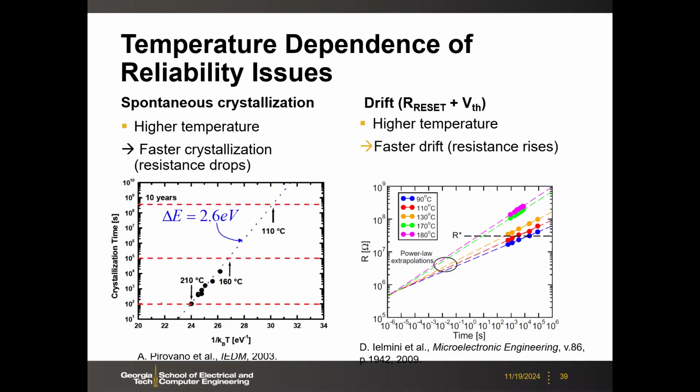That means the device tends to move from the high resistance states to the low resistance states. If you have some temperature, that will accelerate this recrystallization due to the spontaneous process.